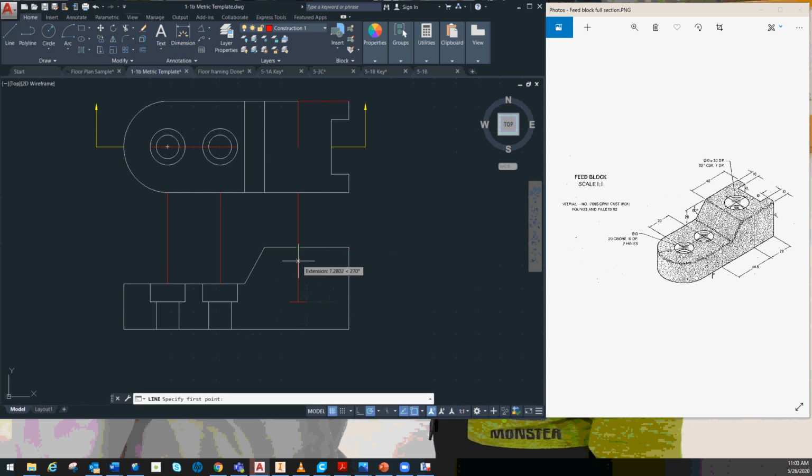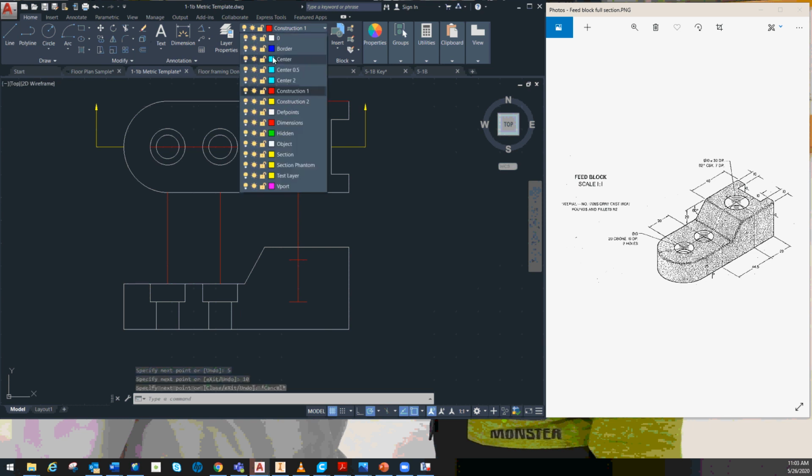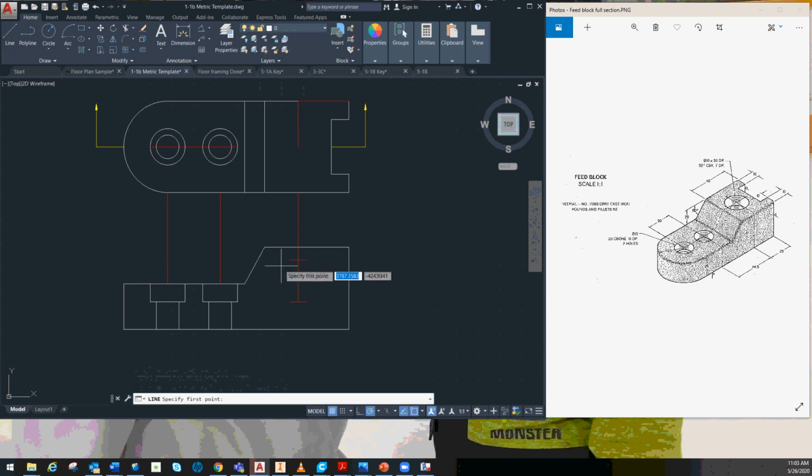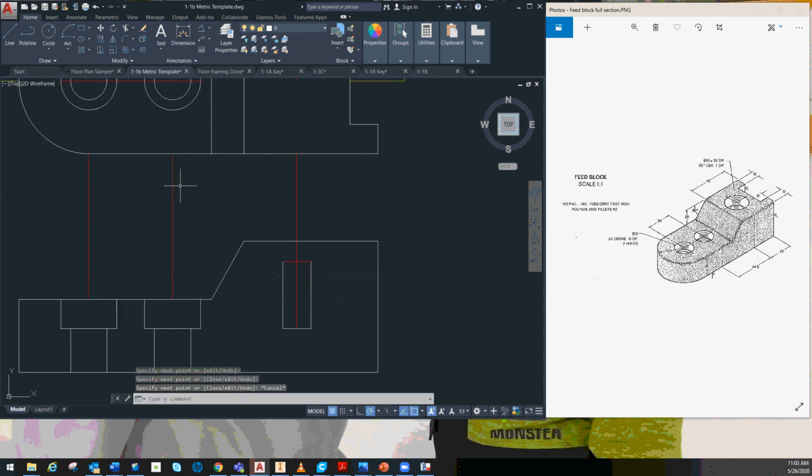And we're also going to have a mark. Our countersink says it's 82 degrees at 7 deep. So I'm going to put a mark at 7 as well and shoot this across 5 that way and 10 that way. Okay. Now, if we were to actually put our object layer on that, we would see that we have a shape just like that. Okay. Now it's time to draw our angles for our countersink.